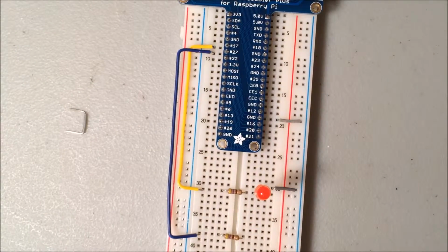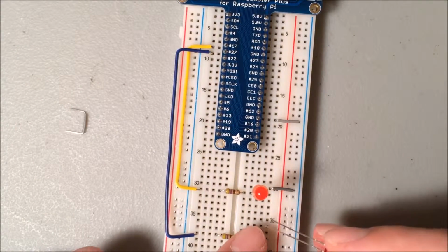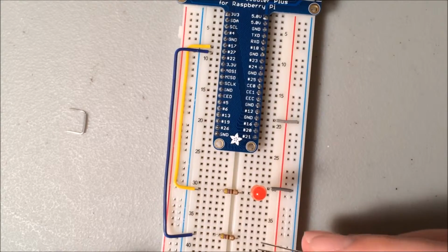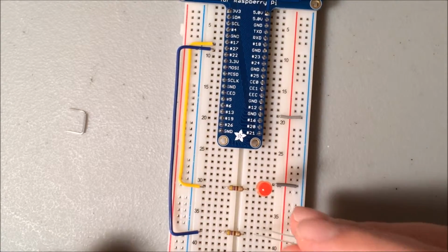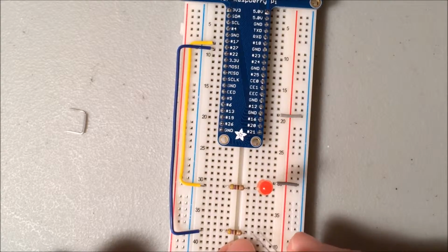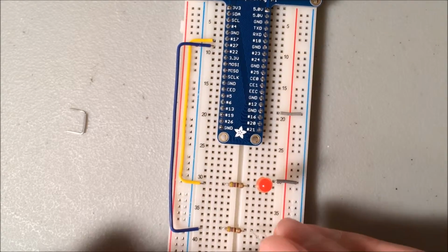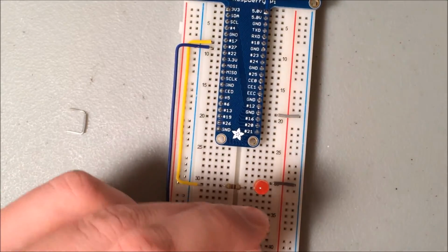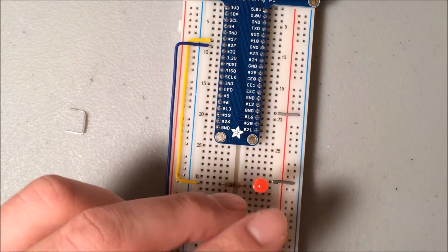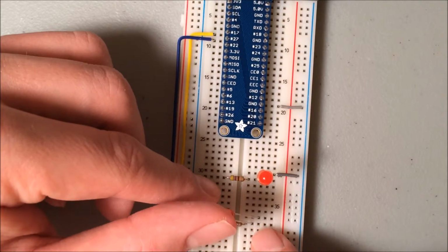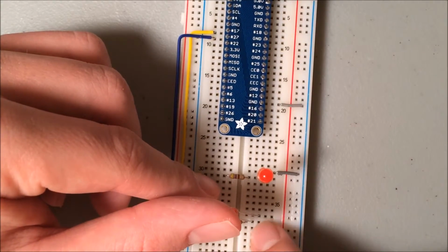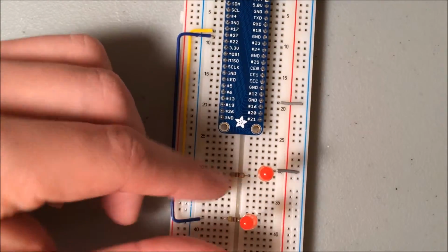And then I'm going to go ahead and add my LED. I want the anode, the longer leg, down towards the bottom here, and the cathode, the shorter leg, just one row above. So I'm going to put the anode in the same line as the resistor, that's row 38, and then row 37 is going to get the shorter leg, the cathode. So I put it at kind of a slant. As you can see, I have it sort of shifting both rows and columns there.